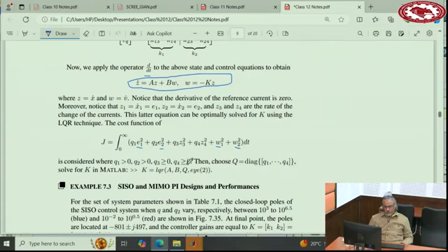And then we just choose Q1 and Q2 and increase them. You may choose Q1 and Q2 equal, because these are really 2 channels and there is no preference between them. So we shouldn't give any preference to any of them. So you increase both of them together, and this one you initially put as 0, and then you fix this one if need be and increase the other ones. So I will show you in the simulation.